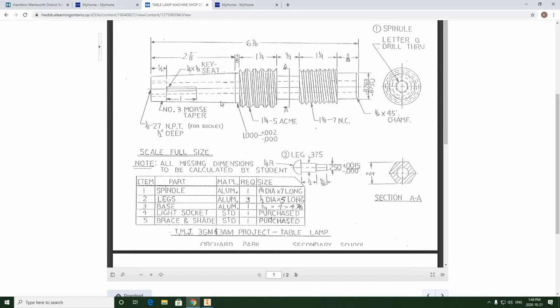We're going to be learning a new modeling procedure to create the tapered shaft here. We're going to be using what's called a LOFT. This is on what's called a number 3 Morse taper. So what is a taper? And specifically, what is a number 3 taper? Well, we're going to have to consult some tables and charts and look some information up. Some of the information I look up for you, and some of the information I want you to search online for while you complete this project.